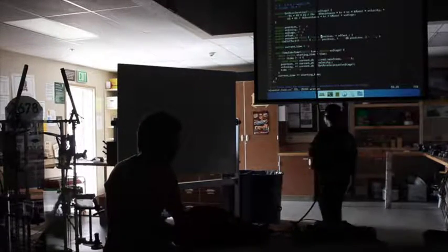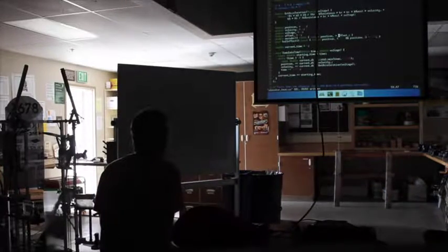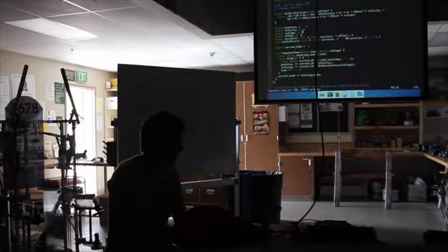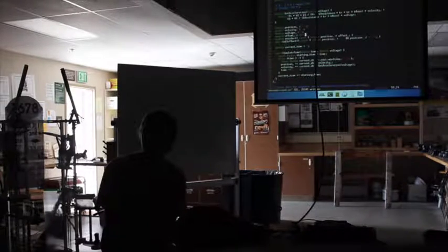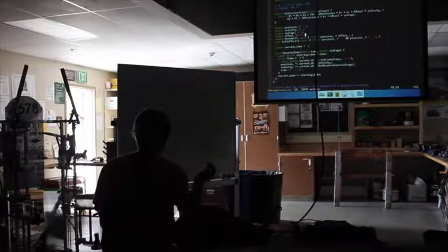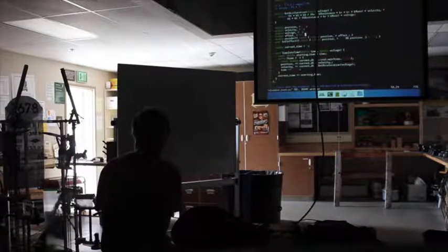So if our position starts out at 0.1 and we have an offset, we want to add something so the encoder will read 0. So we can set our offset to minus 0.1, right? And now our encoder will read 0, but we'll be at 0.1. So we'll start above it, yet read that we're at 0. So this will test to see if our zero encoder is working.